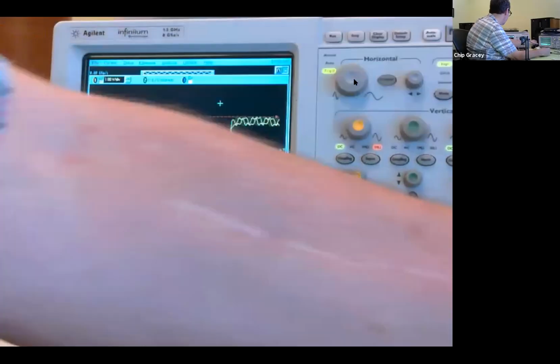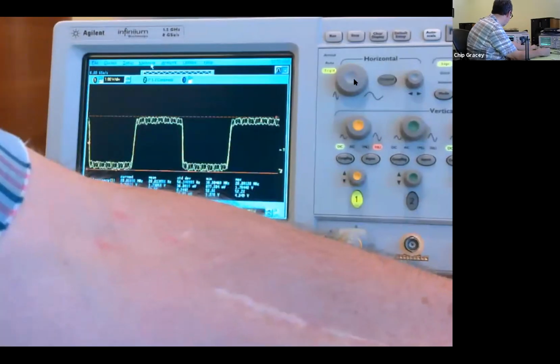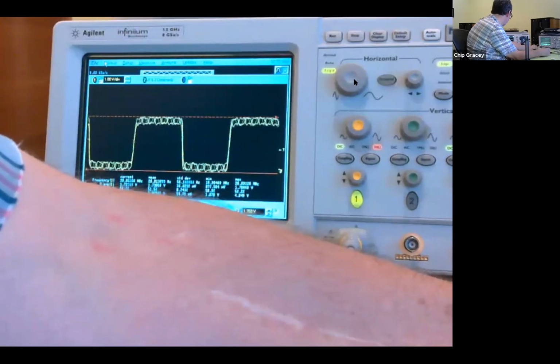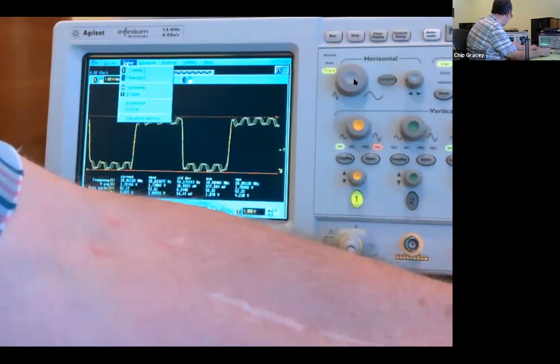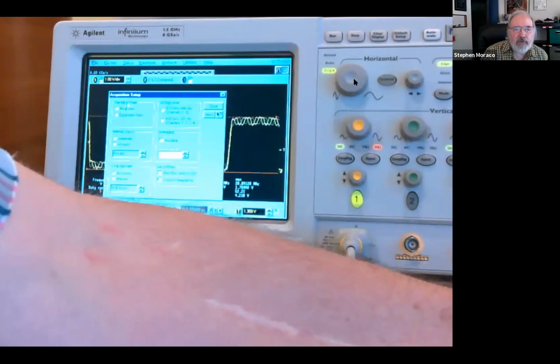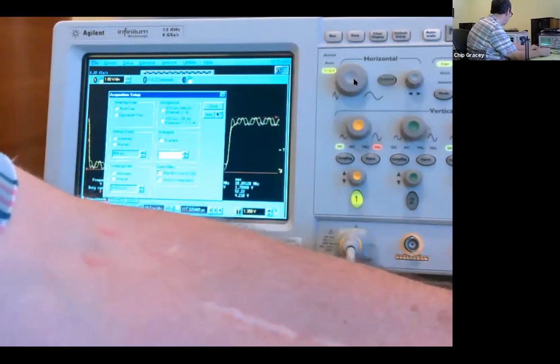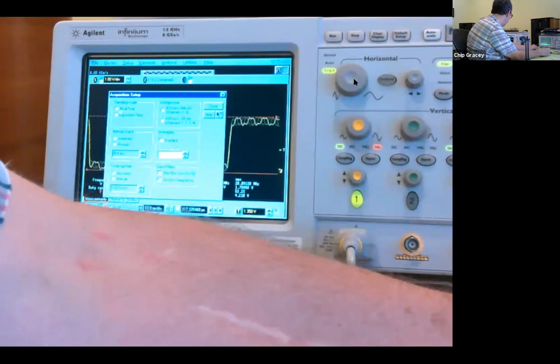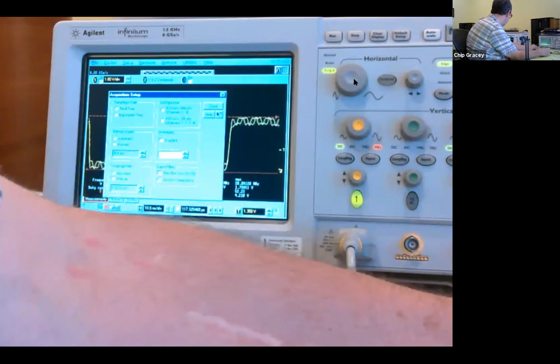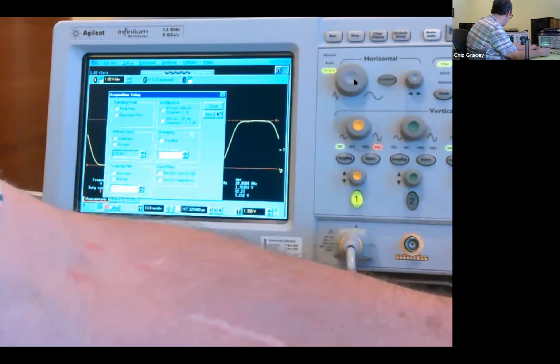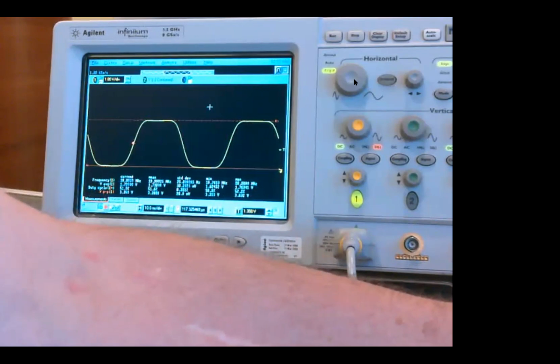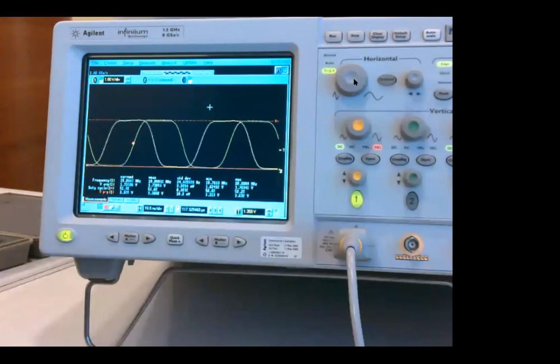Okay, well, if we slow the bandwidth down, let's see here. Control, acquisition? Gigasamples, right? Yeah, it's 8 gigasamples per second. That's what it's doing now. If I switch to manual here, I go down 4 gig, 2 gig, 1 gig. Okay, so here's 1 gigasample. Perfect. You have almost no jitter.